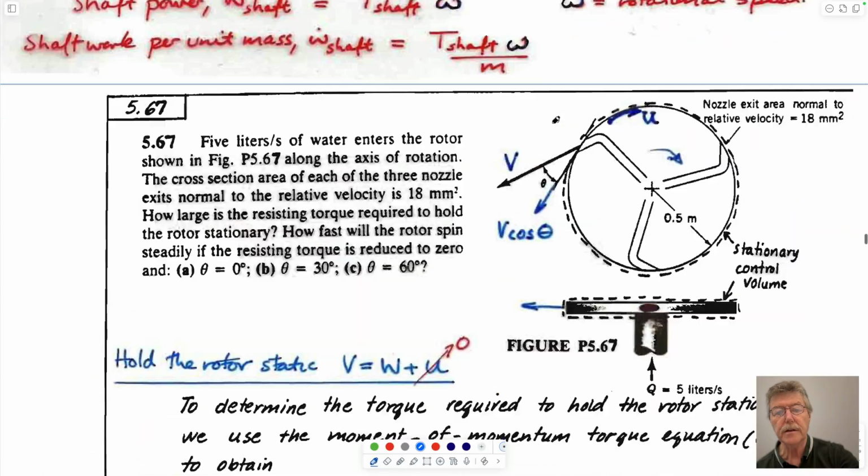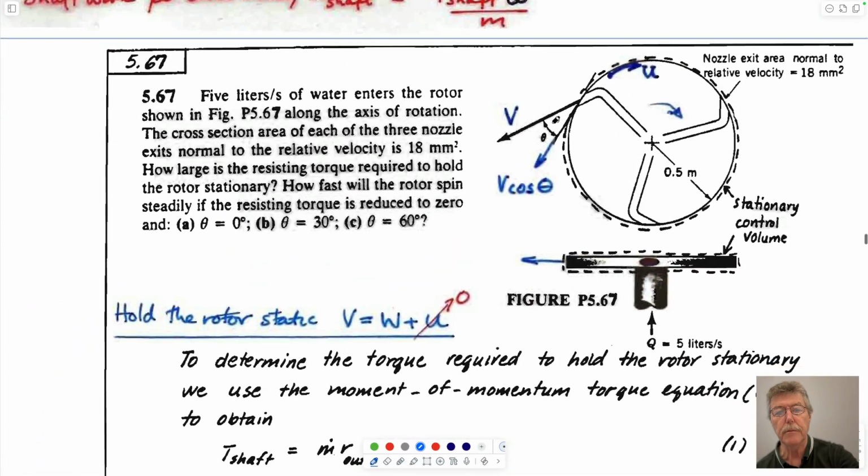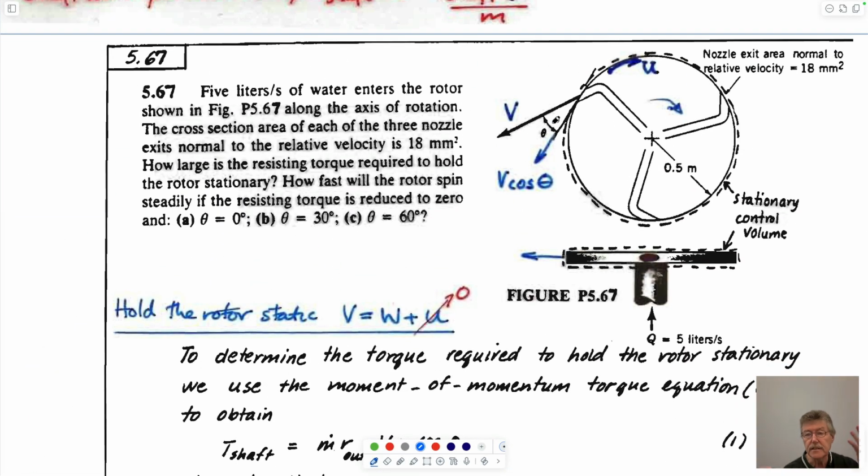Need to know about cross products. This is exactly the problem. So this is the sprinkler. You see it's got exactly the same things that we've talked about. We've done a control volume that goes around it. We have the water squirting out at some velocity. It could be tangential to this control volume or tangential to the arc that the nozzle goes in, or it could be at an angle relative to that, which we can deal with.